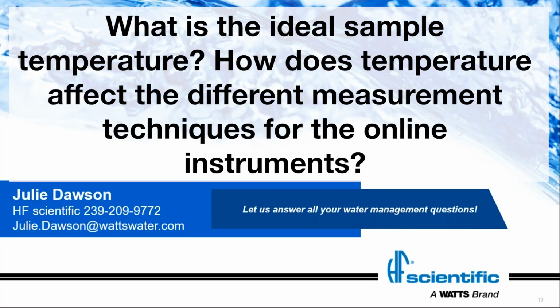As far as the online methods, DPD, again, we want to be within that specification. And also DPD, because we're using typically a cell of some sort, we want to make sure that the temperature between the sample and the air is not causing condensation on the outside of the cell. If it does do that in online analyzers, there are usually desiccants available to put in the online analyzer to reduce the humidity inside. But anything like condensation on the outside of a cell for optical measurement can cause a problem. Because it's an optical measurement, it will scatter light and show up as absorbance. So it can cause the reading to be higher than it should be if there's condensation on the cell for that one.